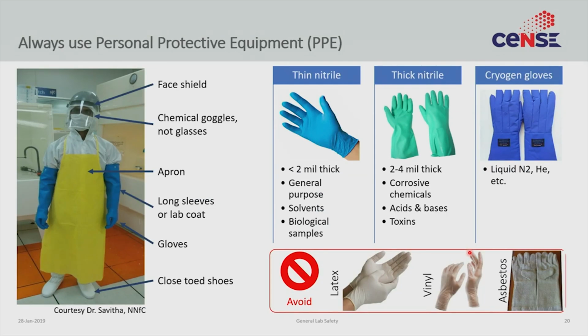With that, let me take a step back and talk a little bit about safety. A lot of semiconductor chemicals that we have discussed today, say hydrofluoric acid, which we had during cleaning, and sulfuric acid, HCl, etc., are remarkably dangerous chemicals, and you need to be very careful in how you use them. The semiconductor industry has very strict standards on how to use the system, use the chemicals, dispose of the chemicals, etc., and those standards must be followed for your safety and environmental safety.